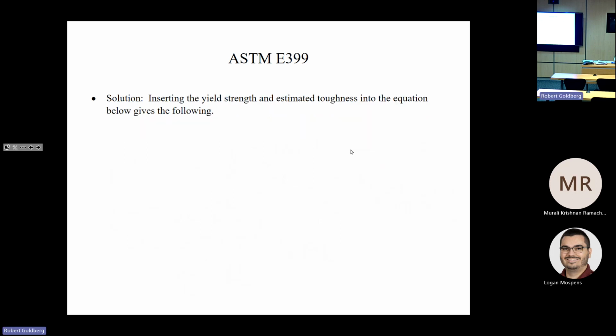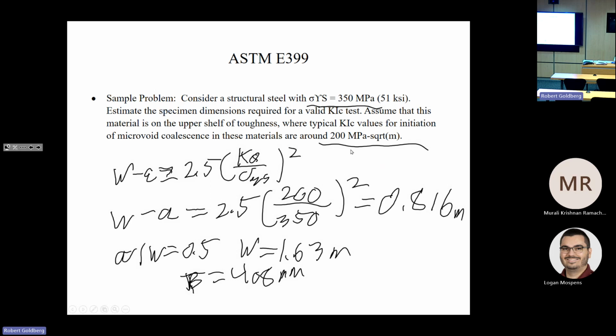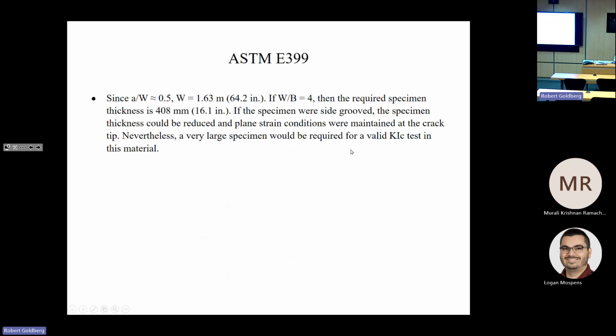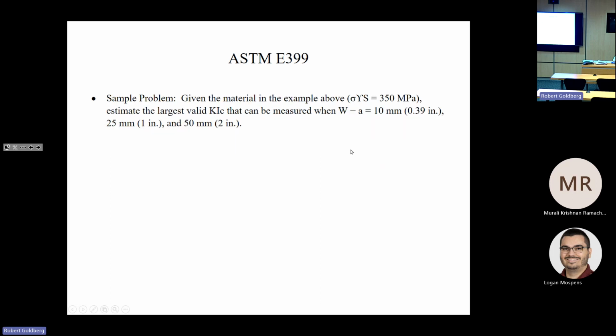So if you put in side grooves, you could reduce the thickness somewhat, but a large specimen would be required for a K1C test in this material.